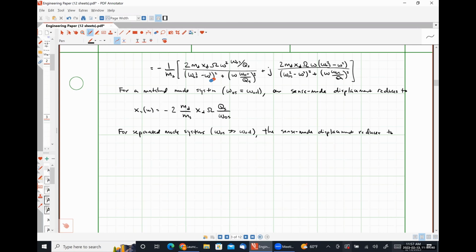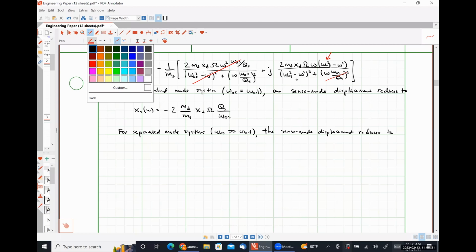So I would argue that our first term here is effectively going to go to 0 because omega squared times omega naught S is going to be much smaller than omega naught S squared here, right? This term of our denominator of this portion is also going to look insignificant to omega naught S squared, okay? And this term should also go away.